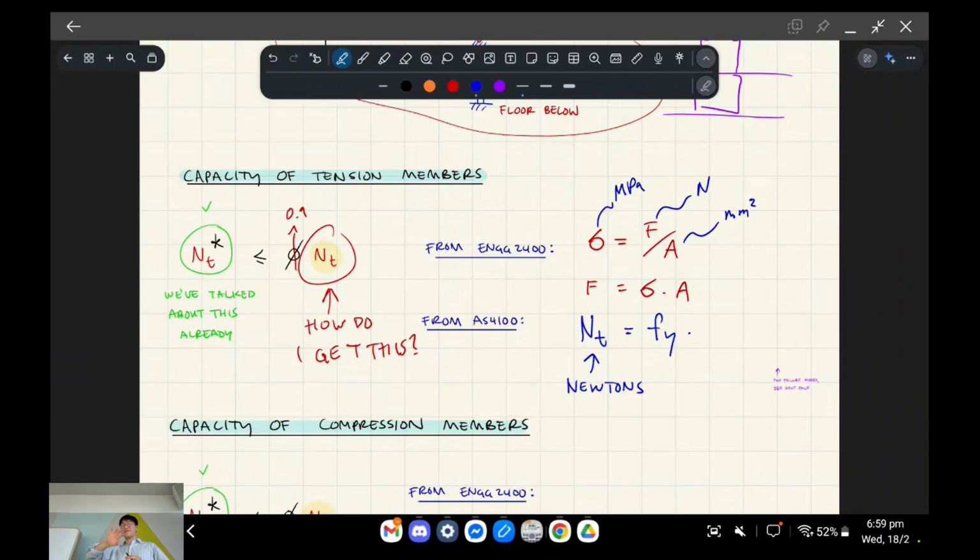So how much stress it can take before it yields and turns into like this plastic cheese kind of shape. And area is going to be AT, area in tension. Just to reiterate, we're talking about tension. Pretend there's a bit of steel and I'm pulling it. There's a certain point where it just becomes like a spaghetti or stringy cheese thing, starts yielding. That's how the metal material behaves.